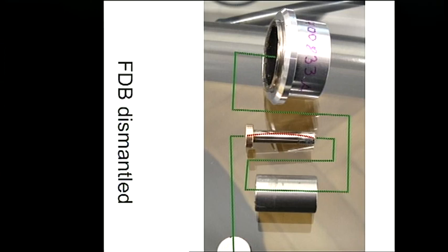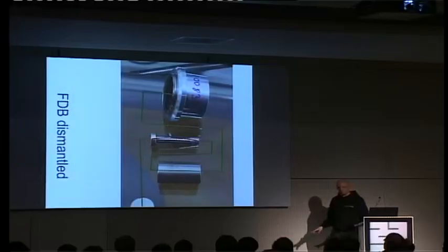And the green line tells you how these pieces go together. And the red line tells you this one, even if you can't see it on the photograph, but I can tell you from measuring it, it's a bent spindle. And the bent spindle goes into the bearing case, and it's stuck there, and you won't be able to turn the hard drive ever again.